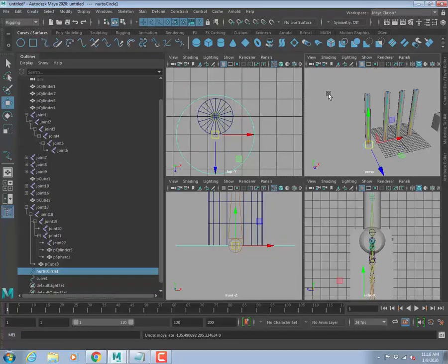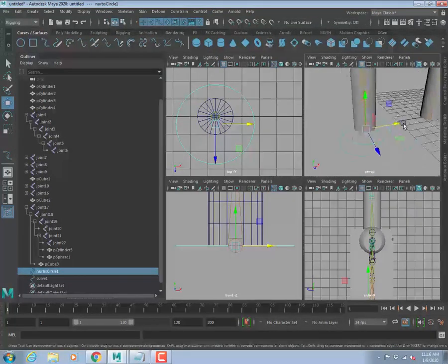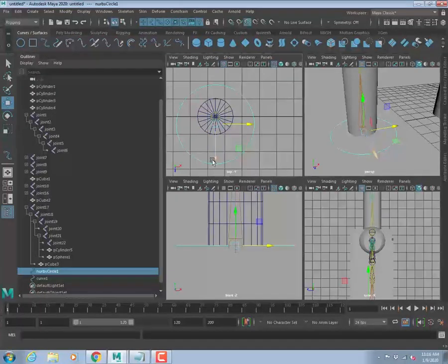Because when I press V and click and drag from the top view, whatever point it can see, it will just snap to. So if I just want to move in one axis, you choose that axis. Currently this is at the ground here, right? You press V, click only one direction, the arrow, drag it, and then drag again, like that.